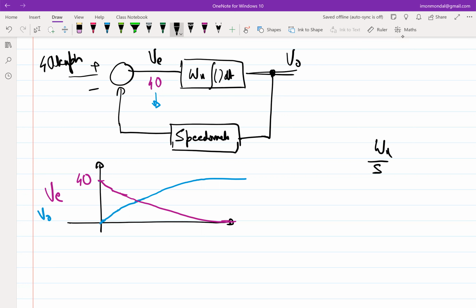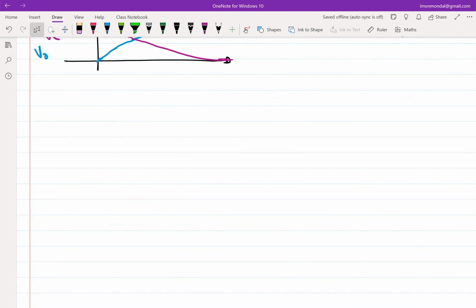So now let's gravitate towards the electrical analogy of this. We would like to make V naught equal to K times Vi, where K is greater than 1. Let me take you back to the process of synthesizing a negative feedback loop. One of the first things you do is define what is desired and what is actual, because only then can you take a difference. In this case, I know that my desired output is K times Vi.